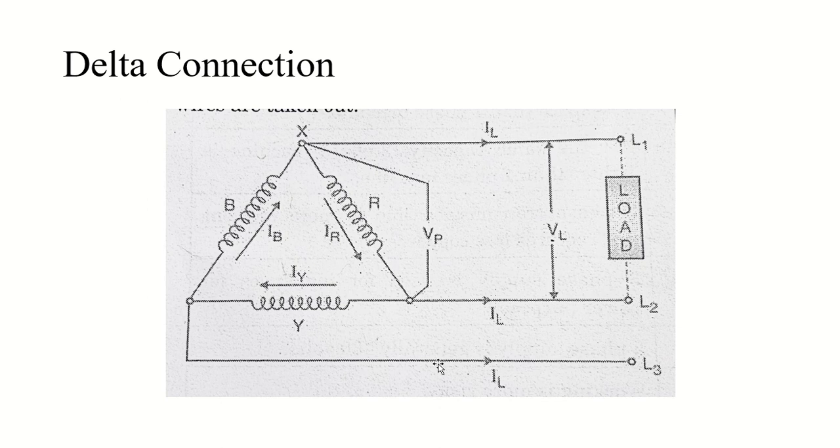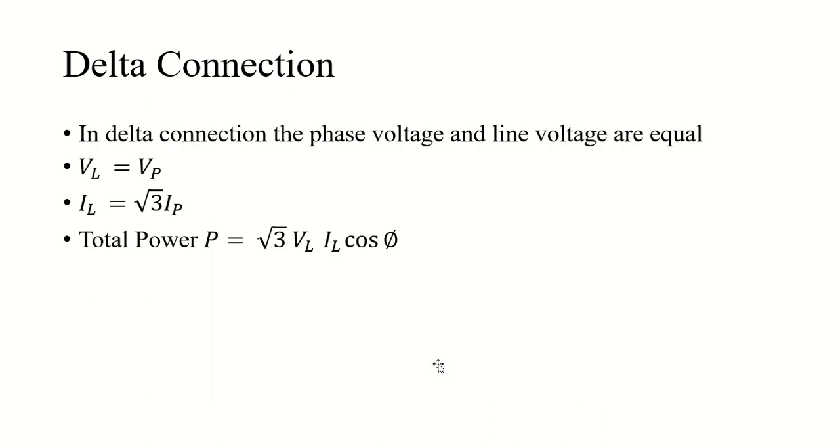So delta connection will be used at transmission. When power is generated, a star-delta connection is provided there. And after transmission, when power reaches our distribution system, there is a delta-star converter given there. It will convert my three phase delta into three phase star connection.